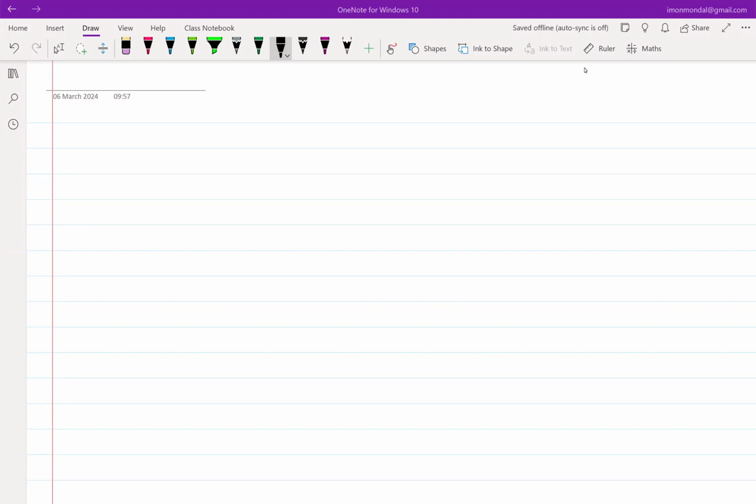So we were looking into biasing a transistor using a constant current source, and one of the ways of biasing that we explored was this. The reason that this works is because if the threshold voltage of the transistor changes or the mobility of the transistor changes, then the VGS adjusts accordingly.